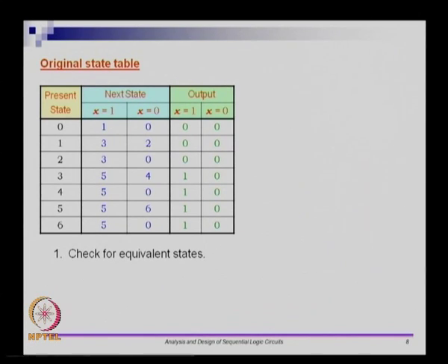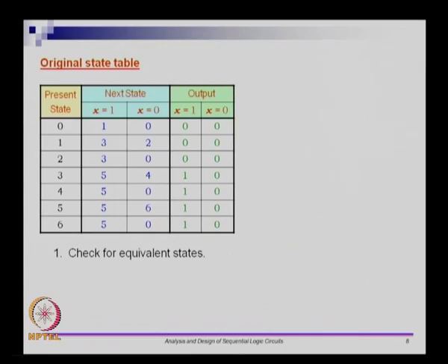So what is the definition of equivalent state? Two states are said to be equivalent if on the same input they give you the same output and they also move to states which are either the same or equivalent. So this is a loaded definition. Let us see the definition in action now.